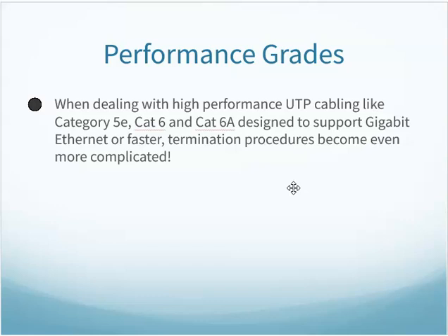We also need to worry about our terminations. As we start working with higher frequency signals, the little things really start mattering. Having a little bit extra untwist on a termination could affect the performance. As I like to joke, because I'm a racing nerd, if I'm going to drive a car at 150, 200 miles an hour, the little things really do matter, so that this machine is going to perform up to its capability. The same thing is going to be true in our cabling system.